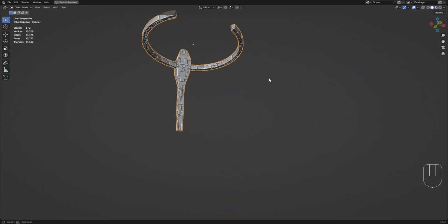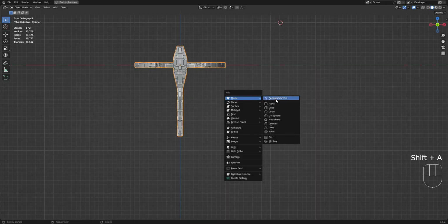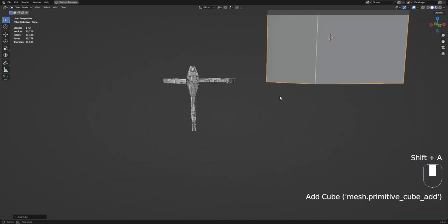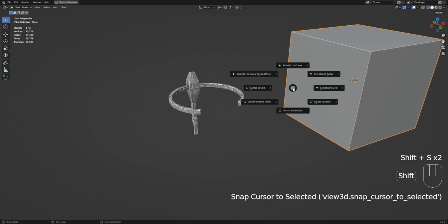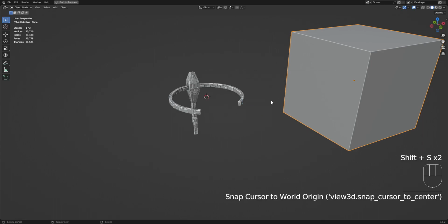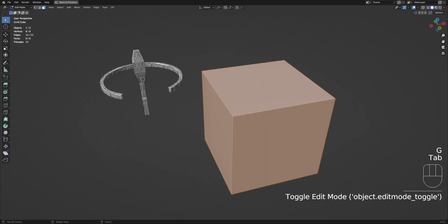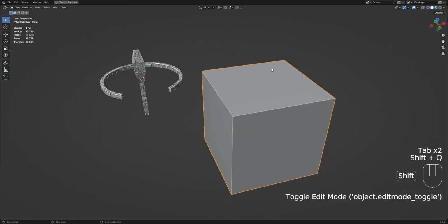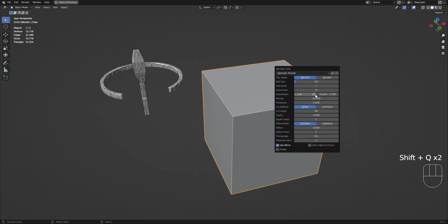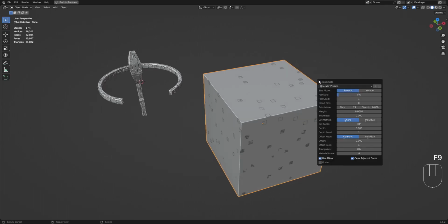Okay, so slice basically is... okay, the 3D cursor keeps jumping off to other places. Okay, so, not random slice, random cells. Let's increase the subdivision. Increasing the subdivision makes the faces generated smaller based on the original topology that is selected.